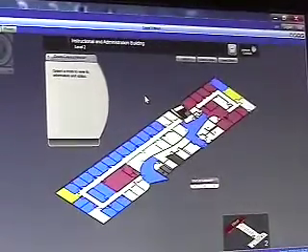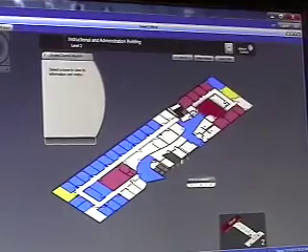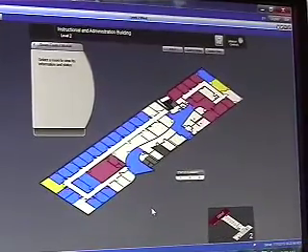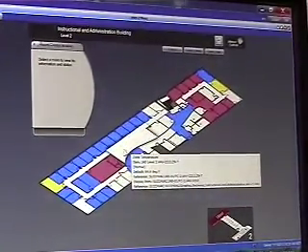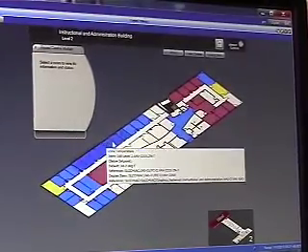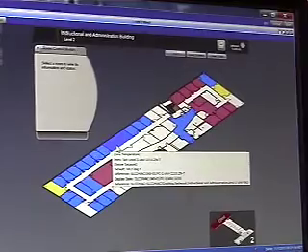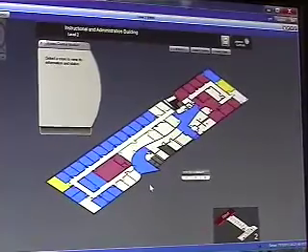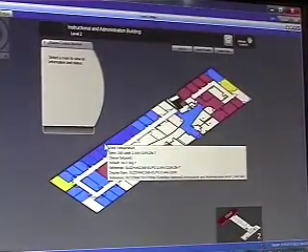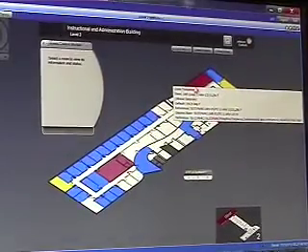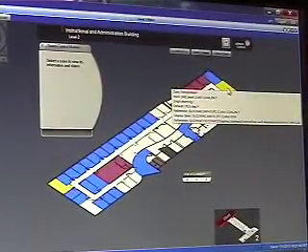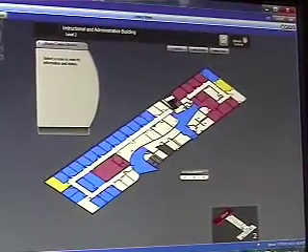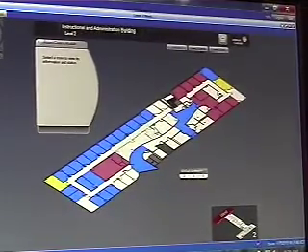Click on the button, then it takes you to a quick overview of where all the different boxes are, or different zones. And you'll see that everything has a different color. If I hover over it, you see how it changes to a dark, which indicates the zone that VAV is actually serving. So even though all these are blue, you can see how they highlight because one VAV box is serving multiple rooms. From here, you can see the different colors, and you're going to see that the blue means that they're cool, that they're below set point. Red means that they're above set point. Yellow means that they're approaching a warning, and the gray, I believe, is just not there. If it was gray, it would be unoccupied.